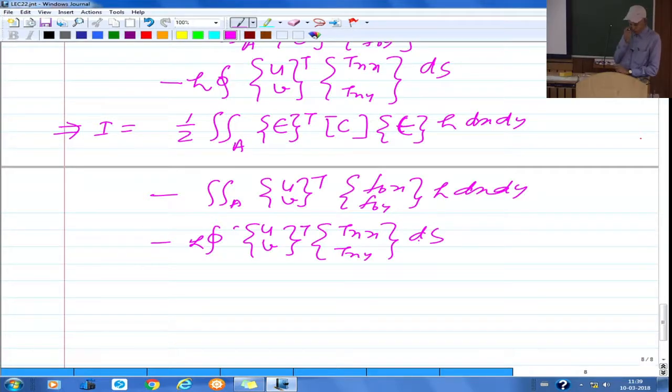In this integral functional, when you look at the definition of strain, the highest order derivative of both the variables u and v is only the first derivative. Because the highest order derivative in the integral functional is 1, the variables themselves would be the primary variables. So in this case the primary variables are going to be only u and v.